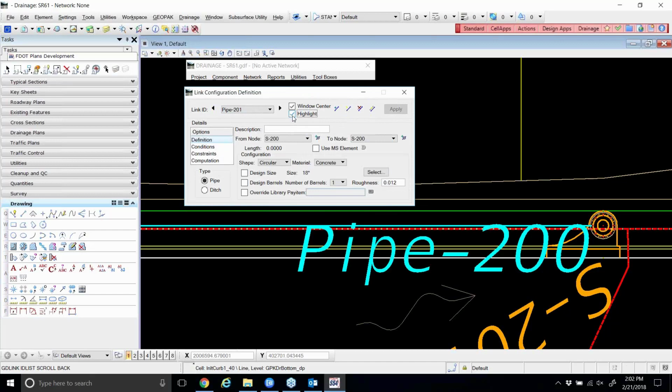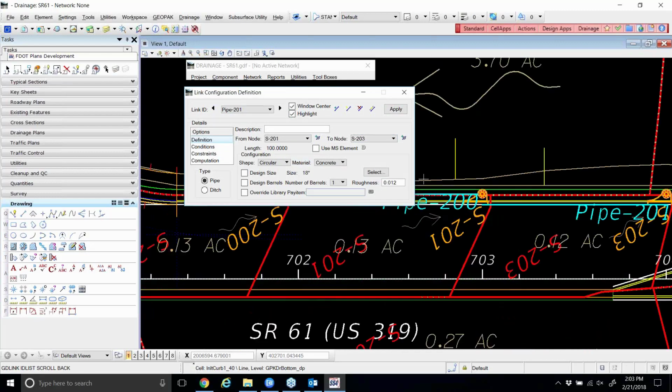We're going to end up extracting the Chapter 6 zip files in the morning. So if you want to be a little lazier on the configuration of these pipes and not click on the small icon and the little red dots, you're more than welcome to skip that. You can just pick the From node and the To node, and the pipe size should take care of it for all of them. What I would recommend is just pick the From node and To node, hit Apply, and